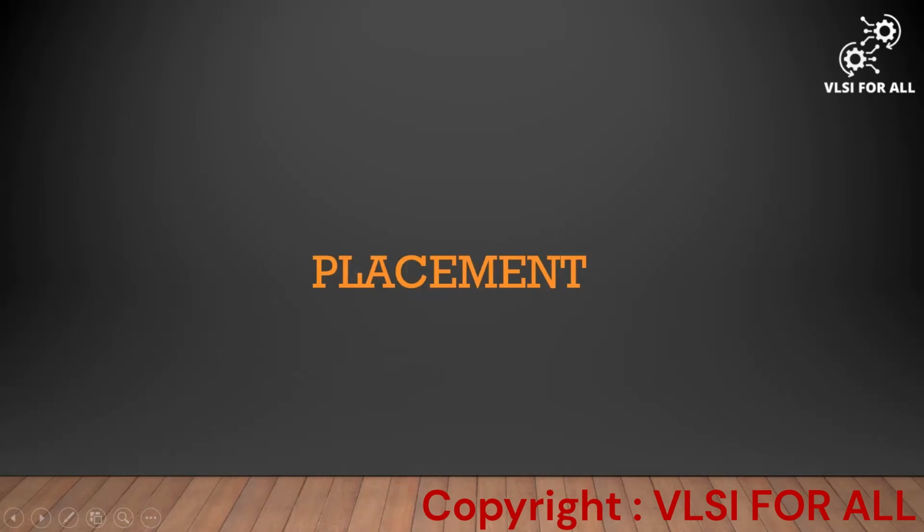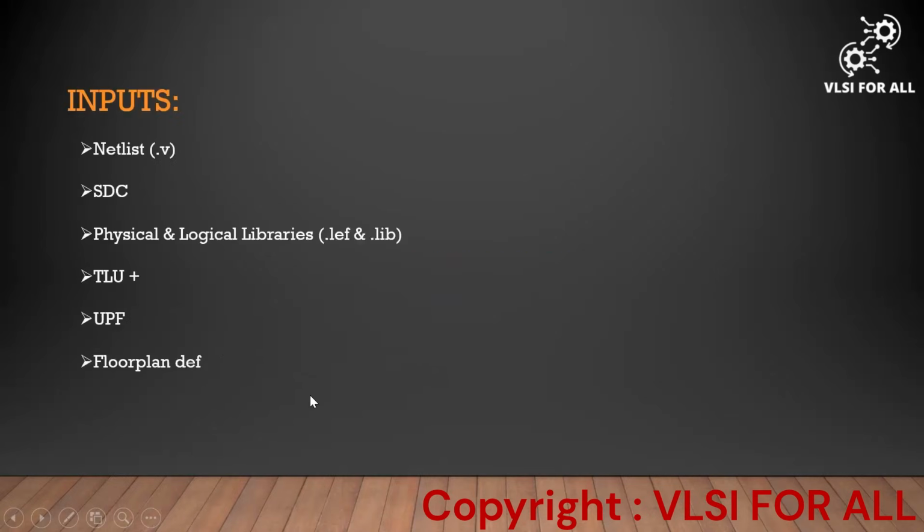Now moving to the placement stage. In placement, the inputs are the netlist, SDC, physical and logical libraries, TLU plus, UPF, and the additional floorplan DEF will be provided here.